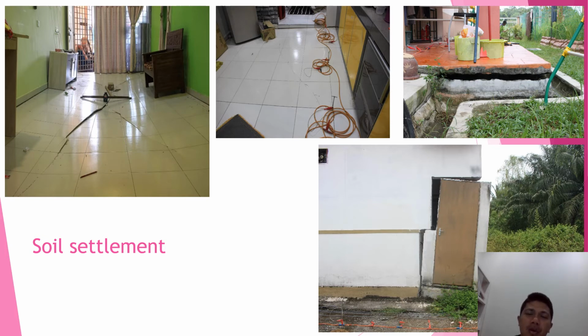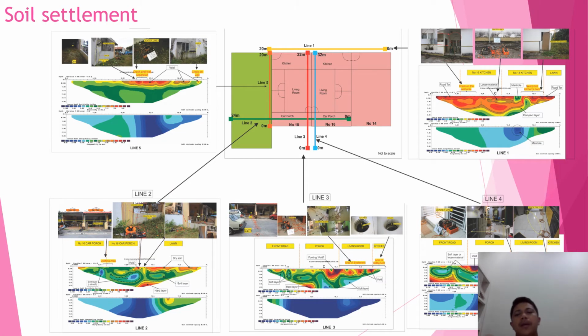Okay, so I used the resistivity method also last time. Here you can see we drilled the tile and then we put the electrodes and then we started the measurement. Same goes to this side. You can see this is the empty space, and then we drilled and put all the electrodes there to get the void area for this settlement problem. And then yeah, maybe this one I can share some results, resistivity and IP.